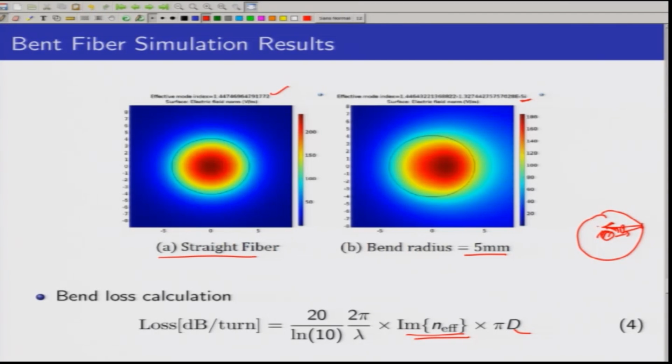So, in order to avoid this circumstance, we add a third layer which is called a PML layer. What this layer does is, all the radiation that is coming from the core will get absorbed in the PML layer and there is no radiation that is coming out. So, we are basically removing unwanted radiation that would reflect back and distort our final output, protecting our results.